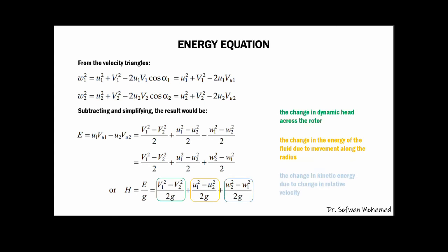And the third term is difficult to quantify or interpret in physical terms. But what we can say is it is simply the change in kinetic energy due to change in relative velocity, which is measured with respect to the rotor.